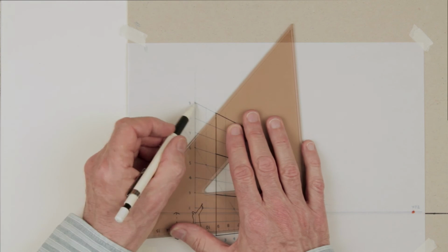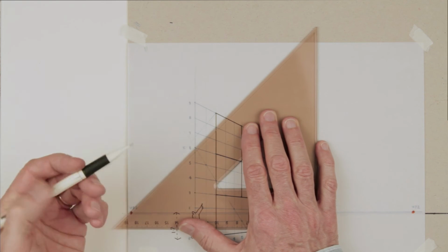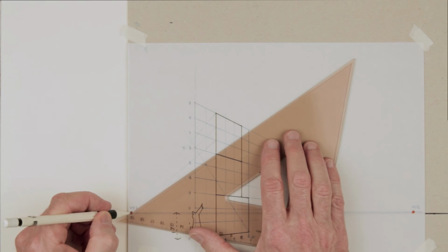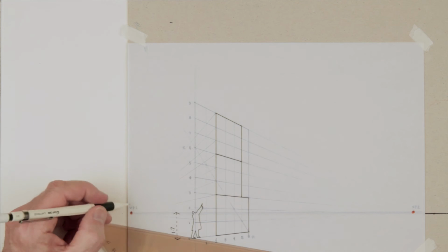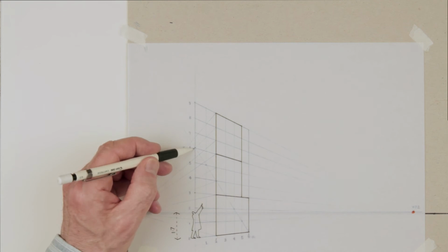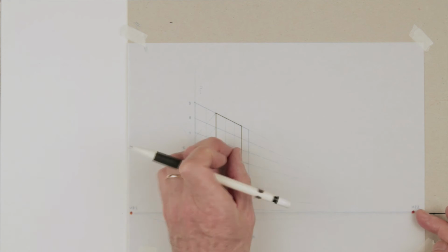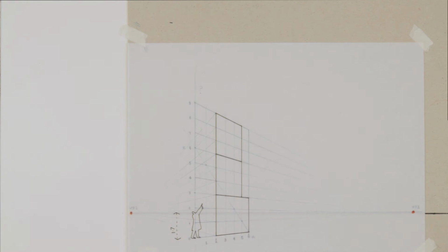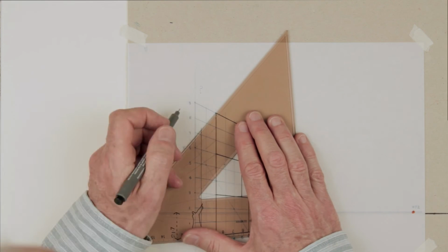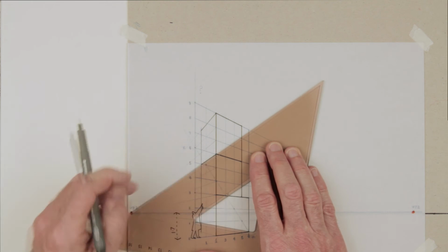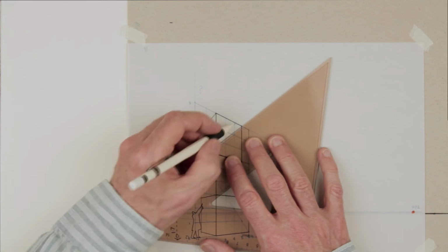Now we can make the front elevation into a 3D structure by projecting corners of horizontal lines 0, 3, 6 and 9 to VP1. Then we estimate again, this time a 3 meter horizontal distance from the leading edge of your shape in the direction of VP1. Draw a vertical line from the bottom of your shape at this point to give you a 3 meter depth. Complete the shapes of all the 3 boxes in 3D, first in blue pencil, then with ink pen.